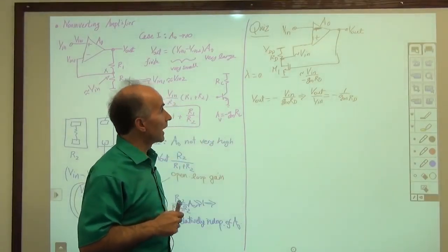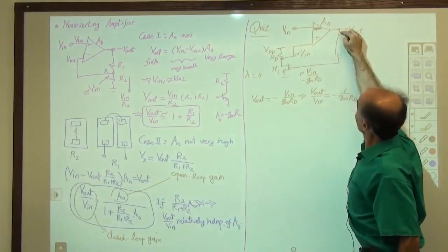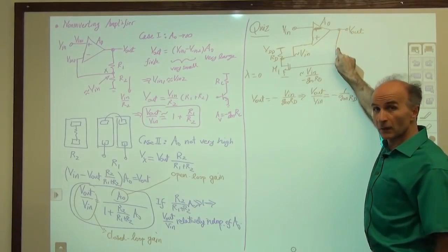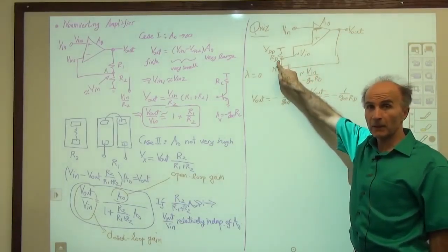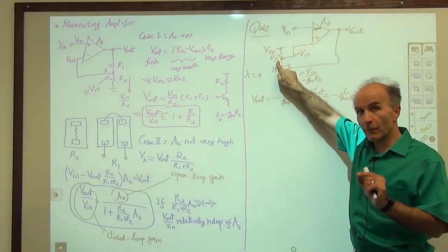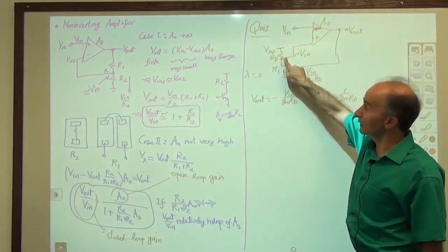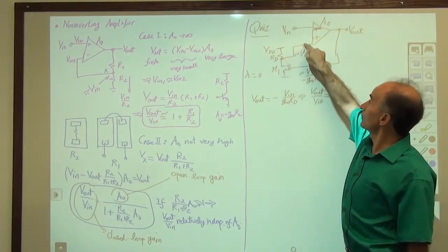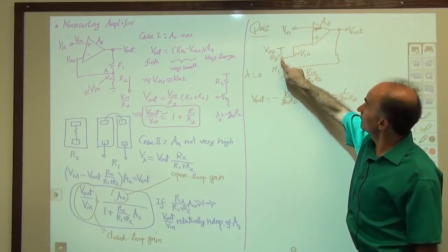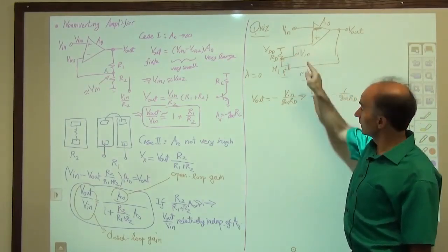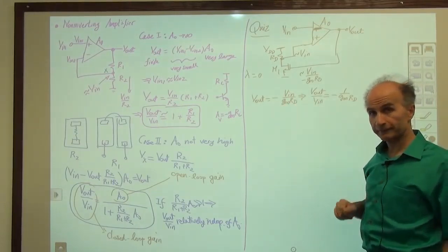Another way of thinking about it is that you could have started from here. We could have said, this is V out. So we have V out here. This must be minus GMRD times V out. So minus GMRD times V out is here. And we know that these two are equal, so minus GMRD V out is equal to V in, so that's what we get.